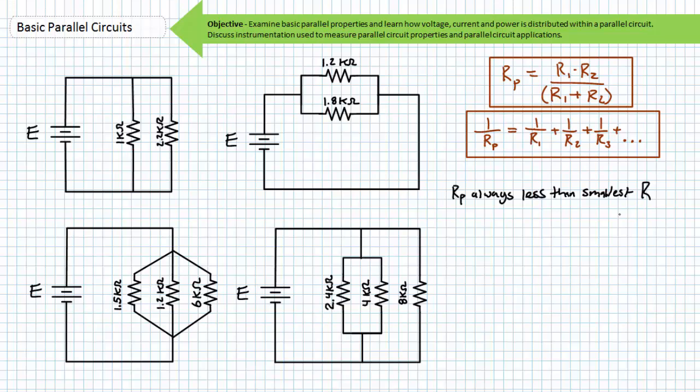Additionally, those resistors composing said parallel relationship can be exchanged without affecting the total resistance. The resistance of a parallel combination can be calculated using one of two formulas, one of which I have extreme affection for, and the other nothing but extreme loathing. Use whichever method floats your boat, but I am telling you, your boat will sink if you use the sum of conductances formula, because it is terribly easy to mess up the order of operations and get a wrong answer.